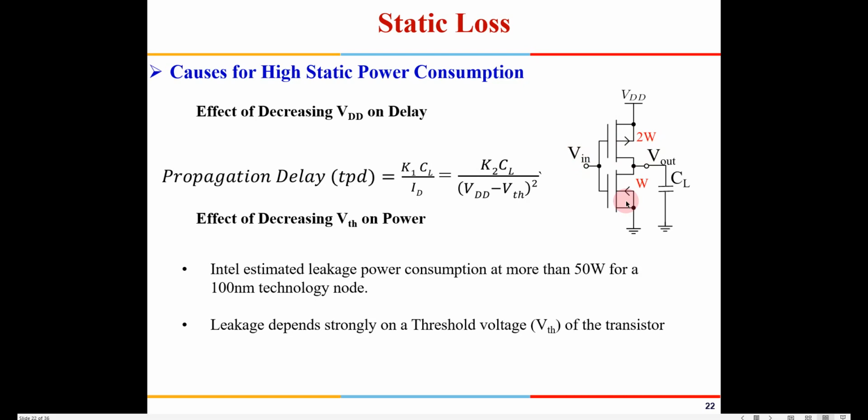If you just keep the voltage high and start reducing the size of the transistor, then the electric field will go very high and there could be a rupture of the junction. So when we make smaller and smaller devices, the voltage also requires to be brought down, so that the electric field remains constant, there is no device damage, and it still continues to work like a MOSFET.